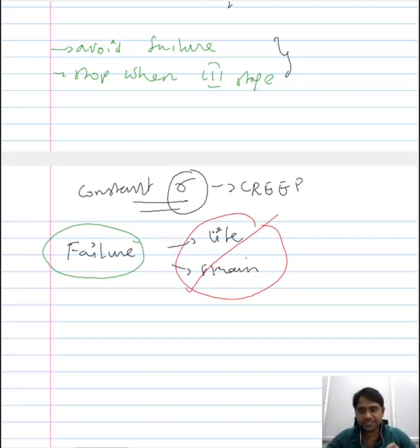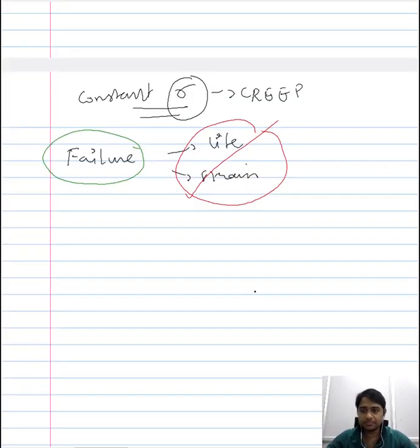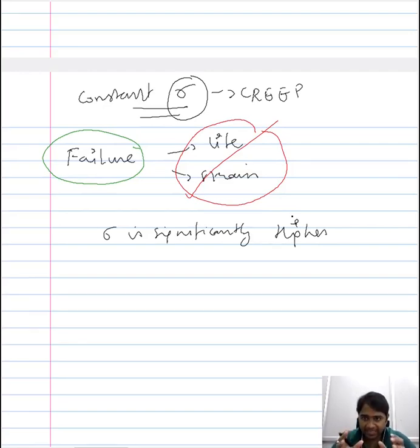So in this test, wherein the failure is of primary importance, the stress that is used is significantly higher than the ones considered for regular creep testing. So what you essentially do, in the creep framework, is that the one factor you would change in order to study the failure of the material at high temperature is to increase the stress to a significantly higher degree.